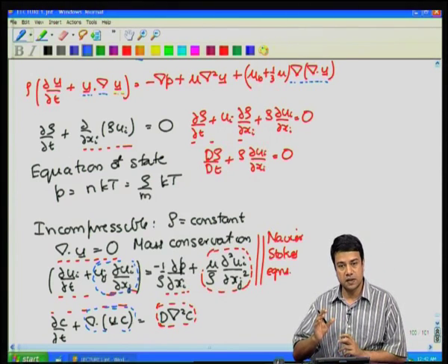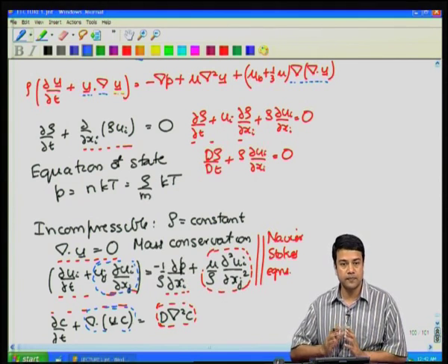So, the big difference is that the convective term in the concentration equation is linear in the concentration field, whereas the convective term in the momentum conservation equation is nonlinear. If you have a linear equation subject to well posed boundary conditions, you are guaranteed that a solution exists and that the solution is unique.